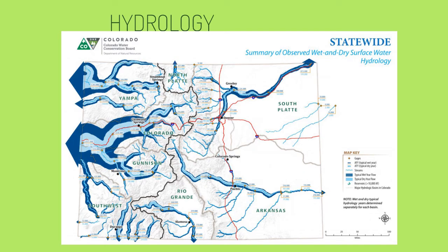Next to slope is knowing the flood-prone surfaces of your site. Sites may have existing hydrology map where you can see where surface water run or flow. Having hydrology map will let us know what part of the site would be flooded during rain or if it will be a flood-prone area. Natural water features are also indicated in the hydrology map like springs, creeks, streams, rivers, and others. Sometimes water tables like aquifers are indicated.